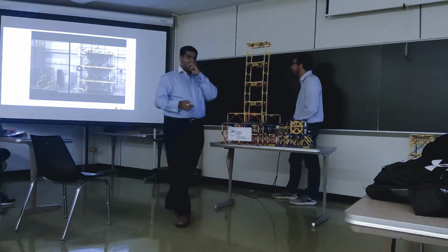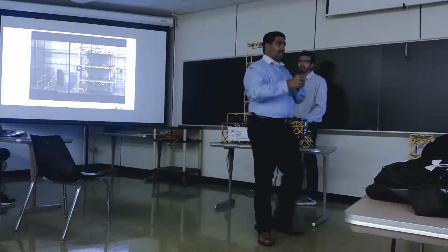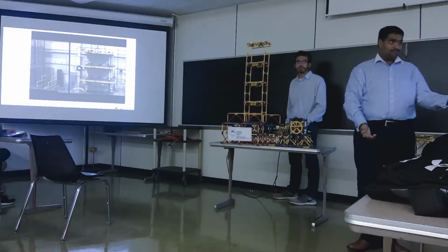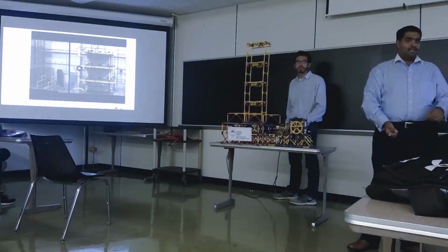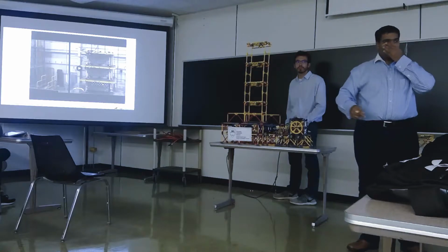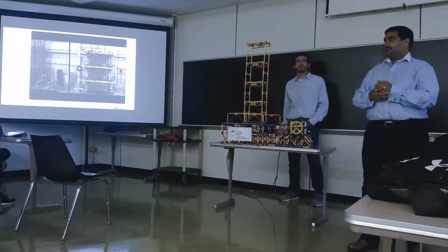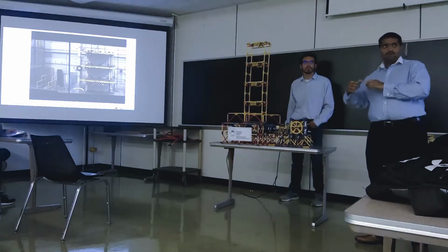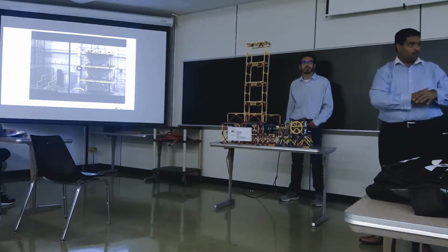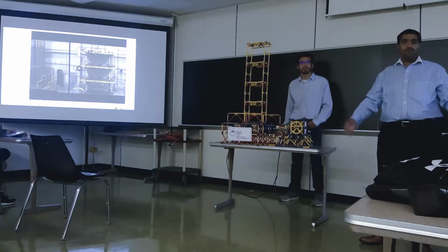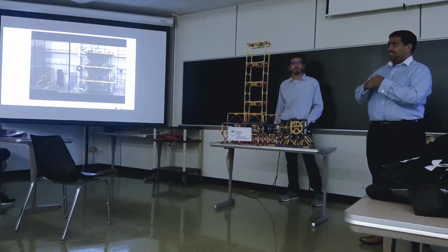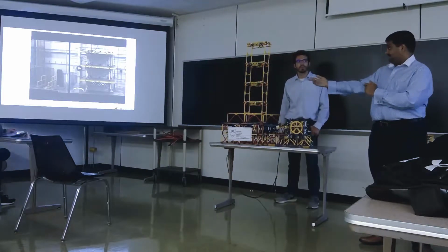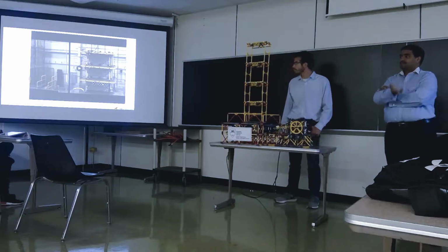So there are different types of input that we can put in that system. We can put a harmonic input and measure the harmonic output at a given frequency. Now we can sweep these frequencies and see at different frequencies how the structure responds. Or the other test that you are seeing over here is more like an environmental load, a summation of different frequency signals. You put that together and you excite the shake table and you see how the system responds.